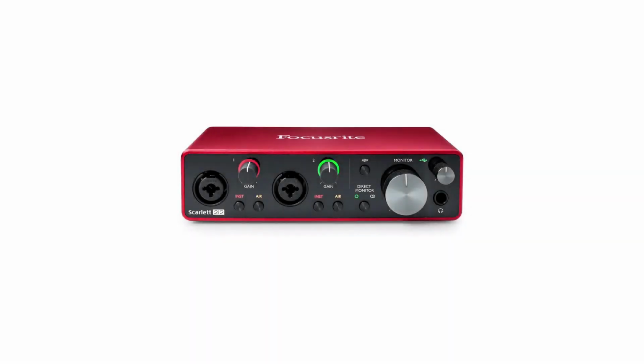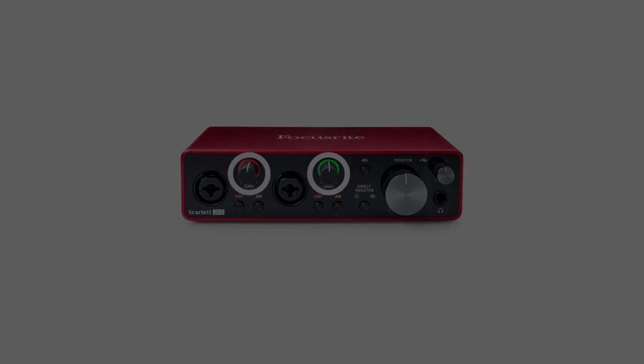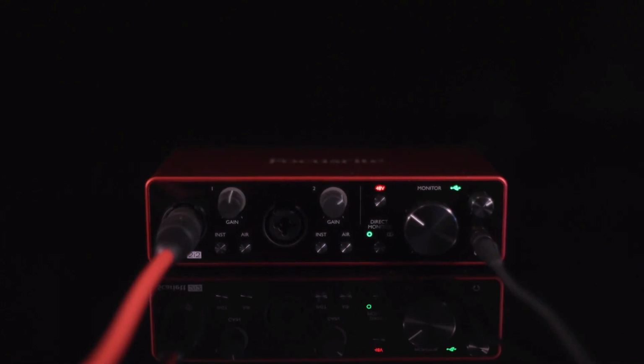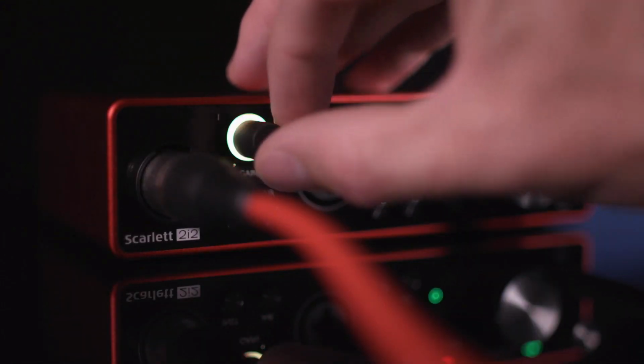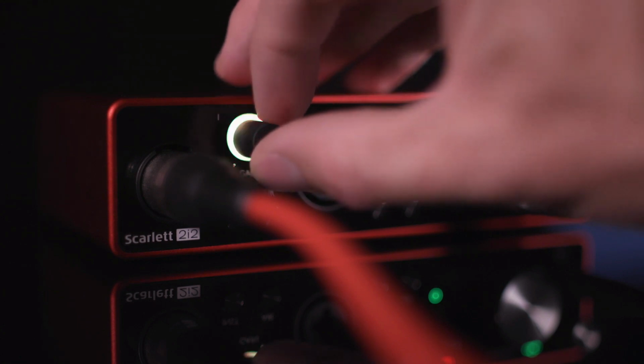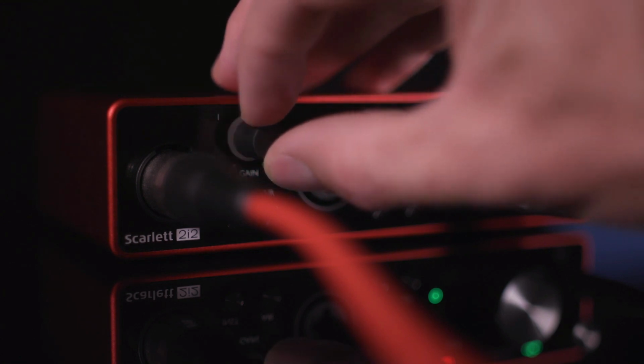Scarlett interfaces include the Halo system to ensure you set a good input level to your audio. Playing a test signal through your mixer, you'll see the halos around the inputs flash. Red means the incoming signal is too loud. You should use the loudest part of your track during this test and turn down accordingly, and set to green, ensuring that this is a suitable input level for OBS whilst leaving headroom.